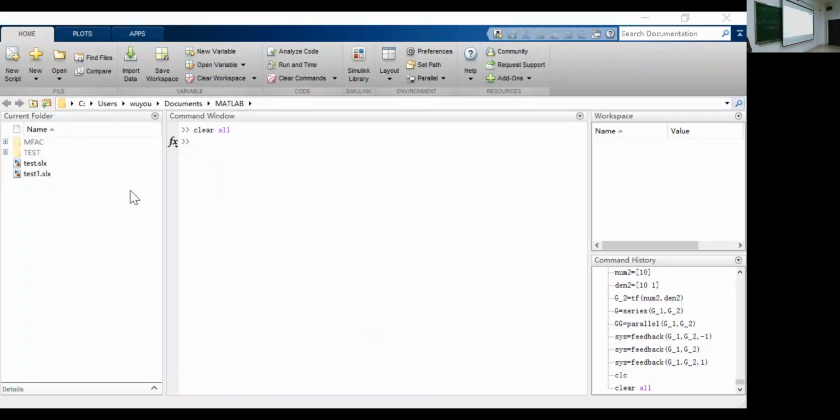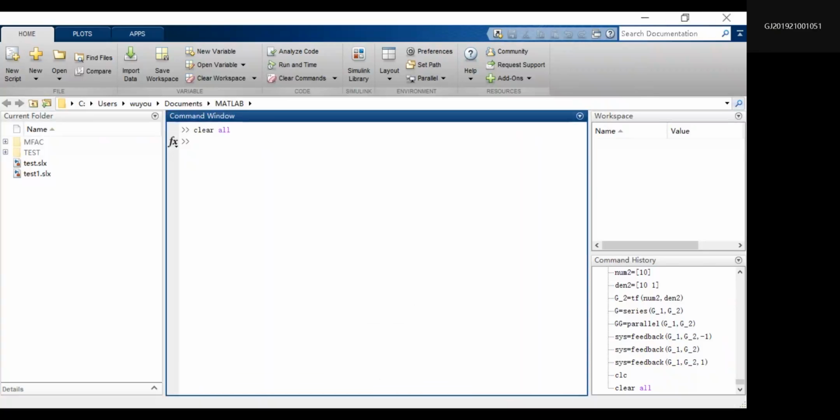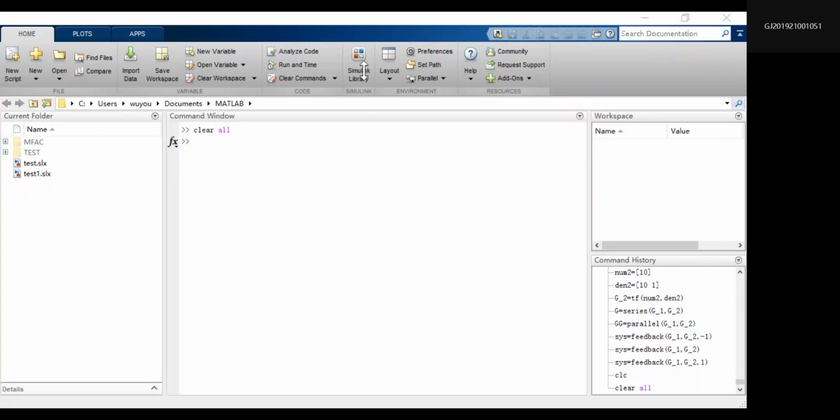If the system is in Laplace transform, then it is a continuous system. So you should find the blocks you need in this menu. Continuous here. And then you see here, it's a transfer function. See the block? Transfer function block. See? And what you need to do is, okay, here. Sorry. Drag it into the blank. And maybe we can.